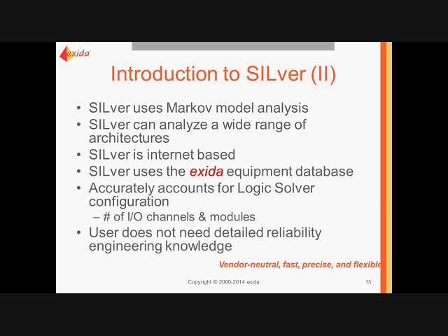Usually if the device has been certified for SIL capability, then there would be a safety manual, and in the safety manual there would be the failure rate data you would need to be able to calculate the PFD average or the PFH.